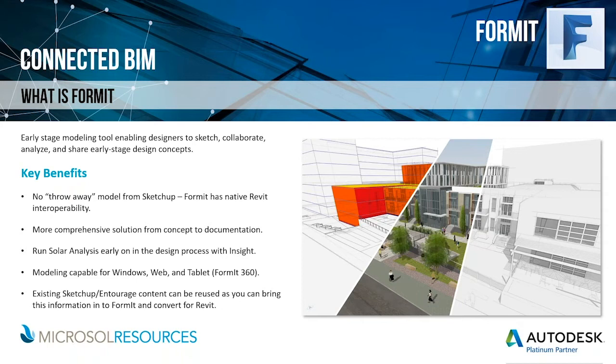And kind of back to the compatibility issues with SketchUp, the two most common ways to import SketchUp into Revit are either by exporting an IFC file from SketchUp and then importing that into Revit, or to create an in-place family in Revit and then use the import CAD command. However, as we already touched on, there are limitations to how Revit treats this data coming in from SketchUp to Revit, and you typically have to do quite a bit of manipulation to kind of make that information usable within Revit.